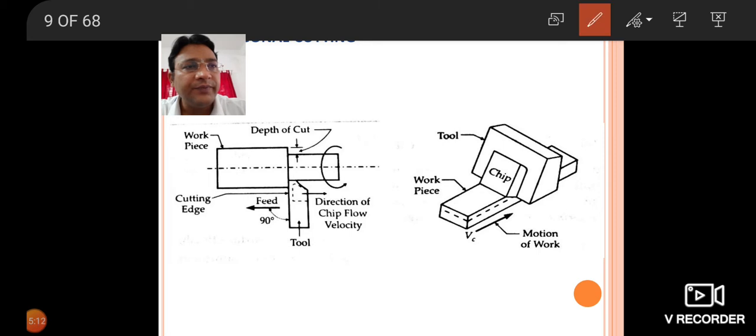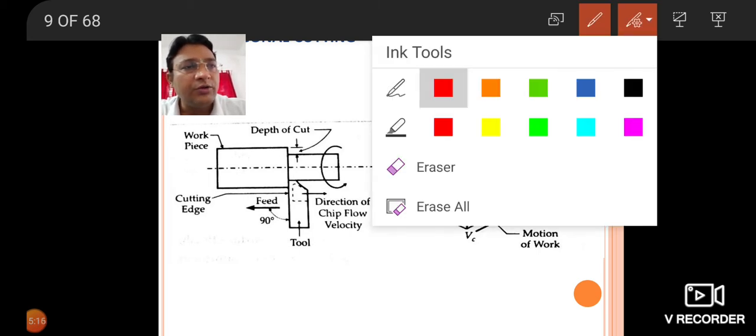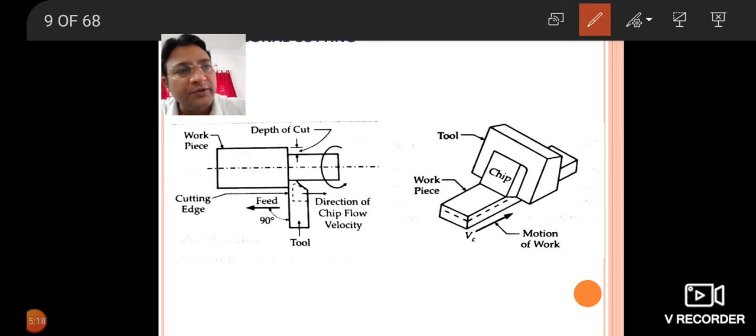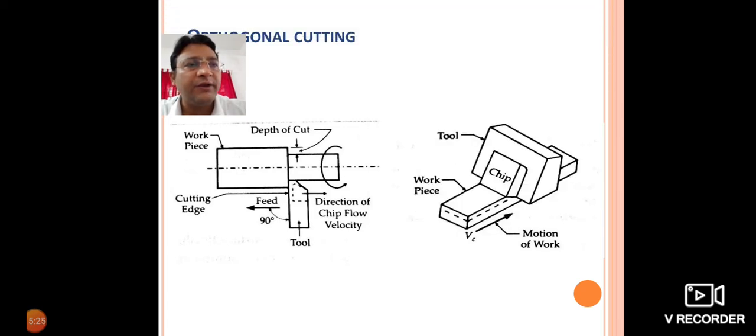Here you can see it is exactly perpendicular. This tool, I am talking about the tool, not about the chip. This particular tool is exactly perpendicular to this direction of feed, but here the tool is not exactly perpendicular to the direction of feed.